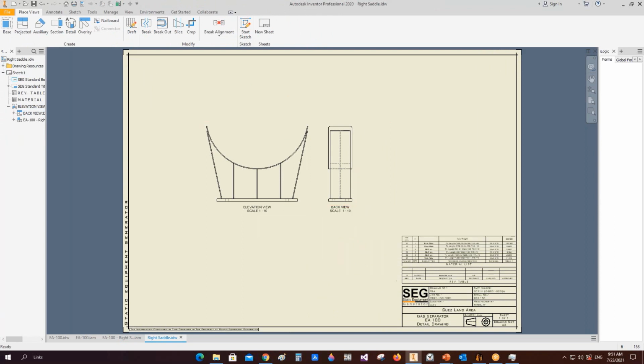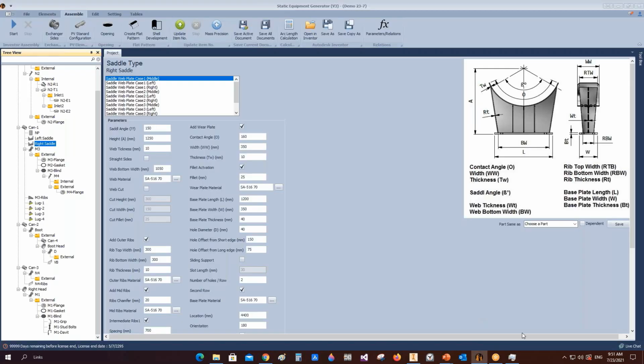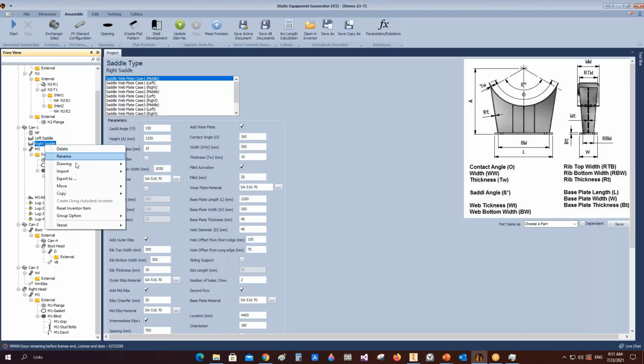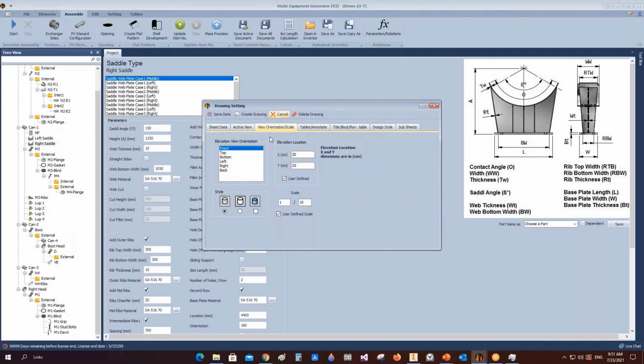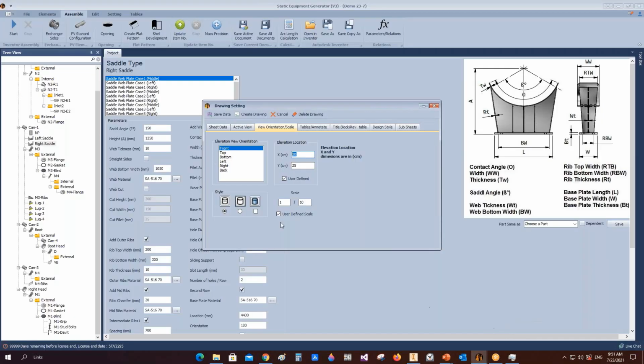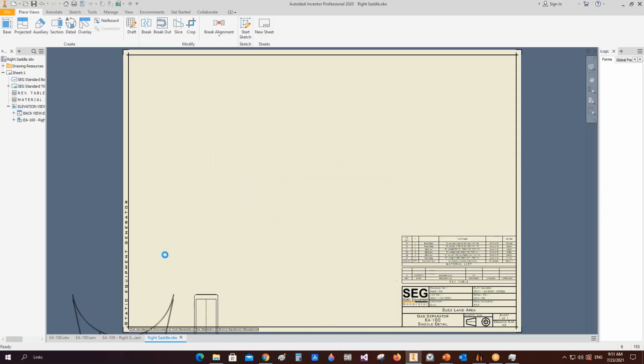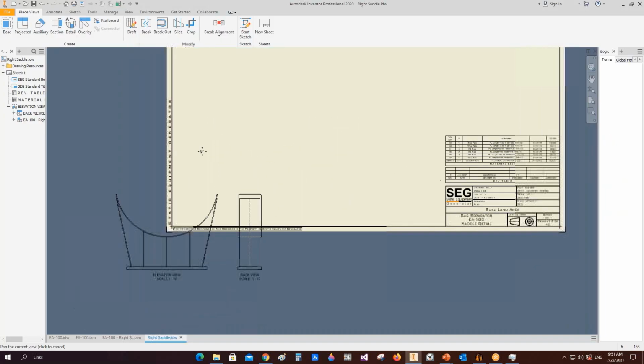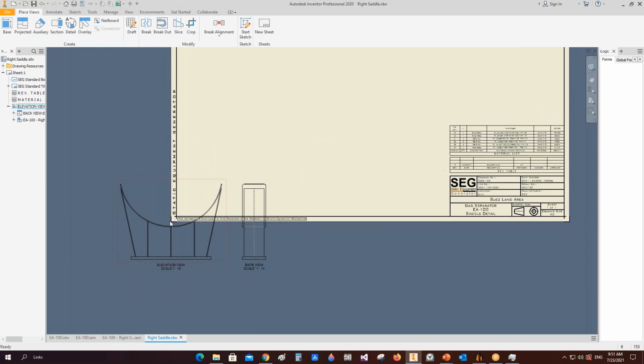If you would like to increase the scale and move it a little bit, as we discussed, we select the element again from the tree and from drawing. Let's move this view a little bit up and to the left hand side, so the scale. To discuss the location, for example, let's make it on 0 and 0, okay, and click on create. You can figure that the location of the first view, the midpoint of this view will be located on 0 and 0.